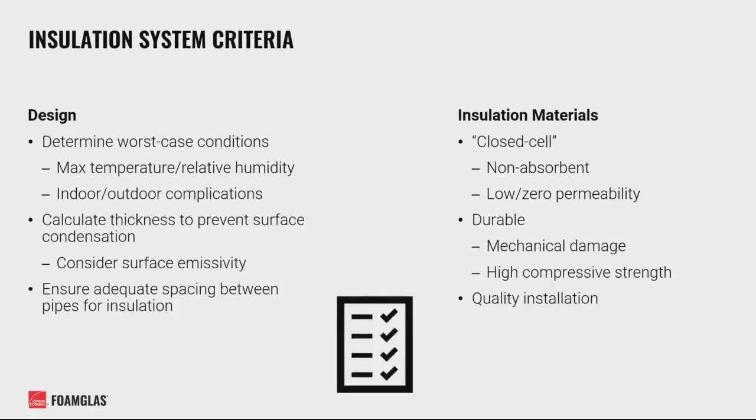As we've now discussed, there are multiple factors that go into designing a successful insulation system for a chilled water application. As a recap, when designing your system, you'll want to always determine the worst case conditions of your environment and plan accordingly. This includes the max temperature and relative humidity to be expected for the environment, as well as any indoor and outdoor complications that may be applicable.